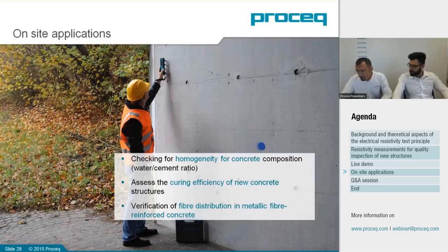Last thing, which is still important here: which method is preferred, surface or bulk resistivity? Well, there are fans of both. Let's say that the geometry factor makes bulk resistivity more precise because there is a very simple shape factor. We drive current through the whole body of the sample and we measure it, no mistake. But there is no way of correlating that with an on-site measurement.